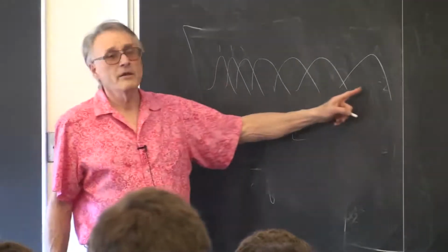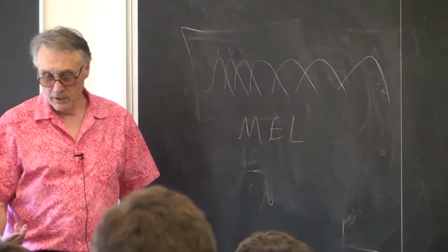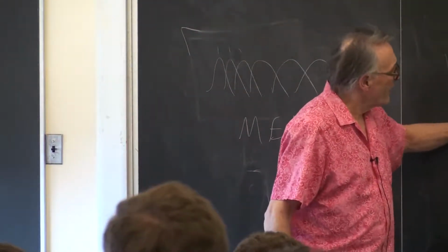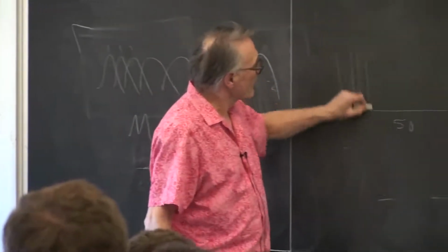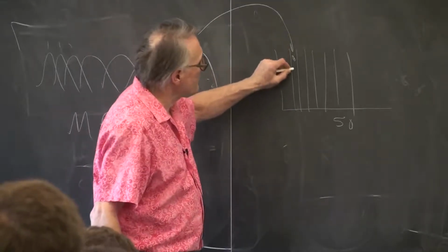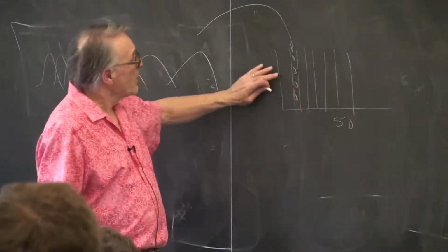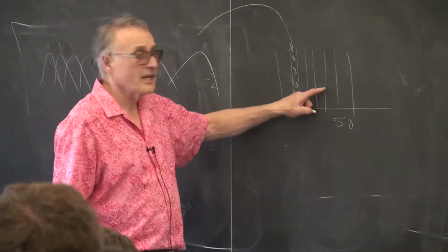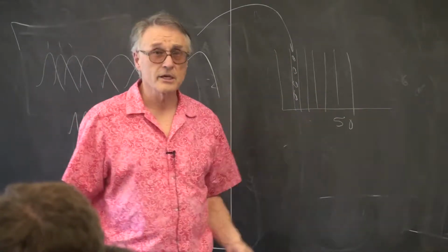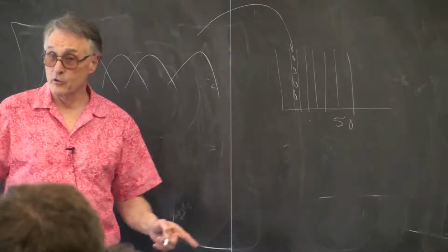So you resolve the signal into a MEL spectrum with a time constant of, say, 20 milliseconds. So that if you wanted to do 1 second of speech, you would have 50 MEL frames all lined up next to each other, where now this spectrum is one of the vertical columns here with a color proportional to intensity or some sort of intensity. Now you have a two-dimensional array of intensities, frequency in this direction, MEL frequency in this direction, time in this direction. Then you use a neural net or some other machine learning to map that onto a word.